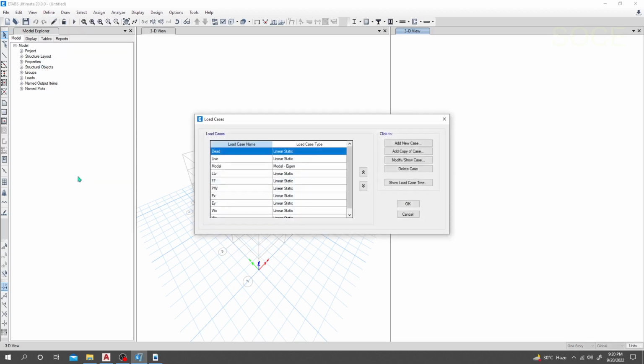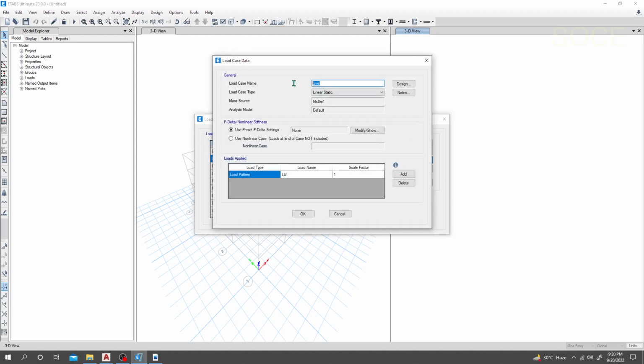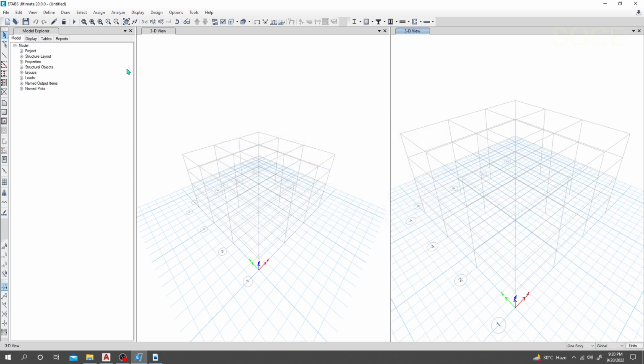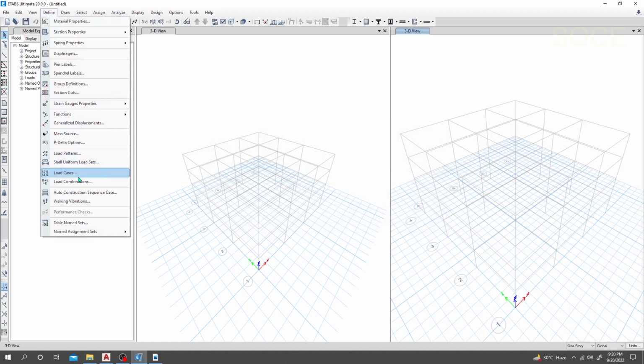And after that we'll define, and here we can take every load we have already defined. We have defined that live load as live load floor. So I'll just go here, modify, and just say here LLF. I'll also give its name LLF. That's it. Okay, so done. Everything is okay. Now I'll go okay. We have defined everything we need initially. Now we'll go for live load. So we'll go for live load in the next lecture.